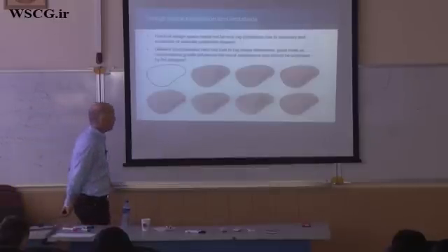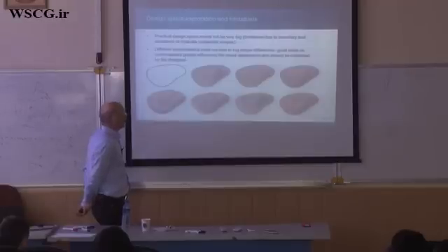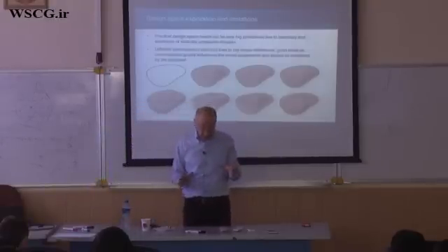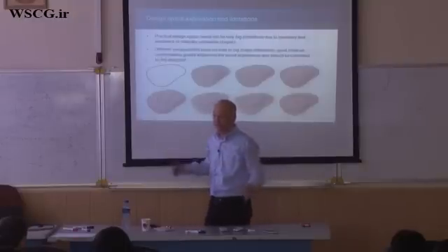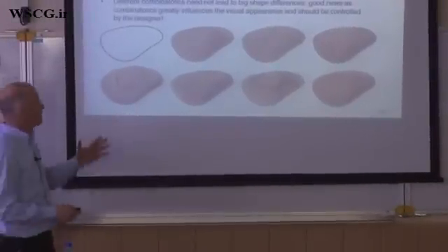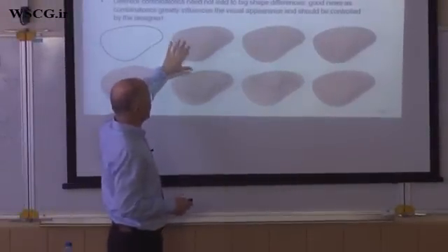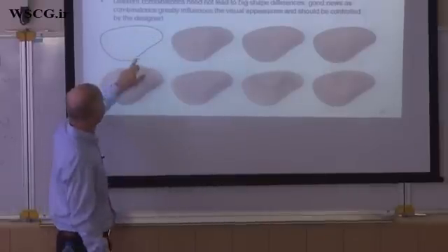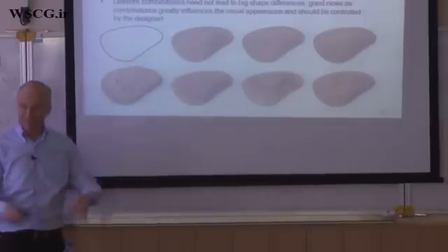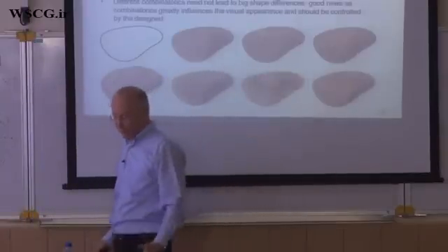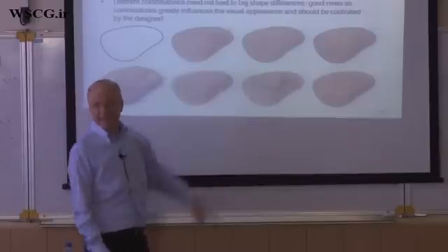Another thing: so far what I had shown you is cases where we have already prescribed the combinatorics of the mesh. Once again, the combinatorics means how things are put together, so the valence of vertices, how many quads are around the vertex, and so on. So we just move around the vertices, we change the geometry, but the combinatorics is fixed. So we can run a test case. We give a boundary, and we put different quad meshes inside this boundary with different combinatorics. And then we do an optimization, say, for flat quads.